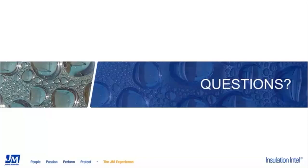Sure. The whole system should be insulated. Any part of the system that is not insulated is going to create the opportunity for condensation. You asked whether insulation would prevent condensation or cause it. Essentially, if you're putting insulation on a system, you're going to prevent condensation, and that's going to help prevent rust because you're going to eliminate the effect of condensating pipes.